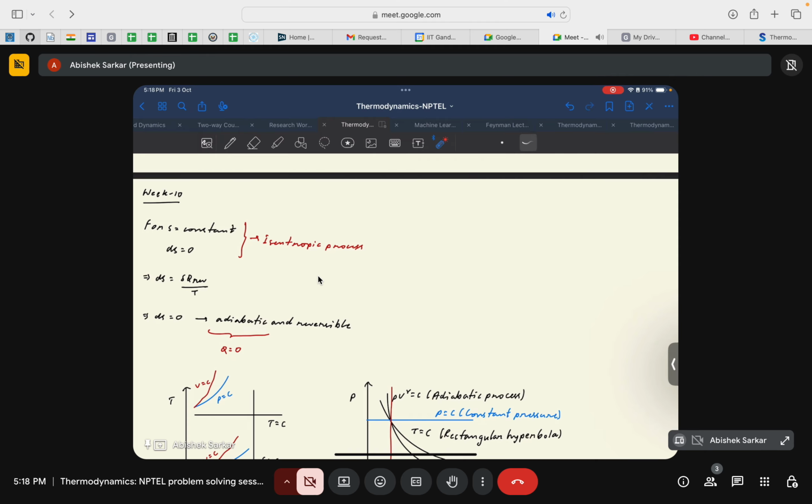Of course, it is, but a proper definition for entropy is clearly defined only for a reversible process, or in terms of a reversible process. So we found out that entropy, or a change in entropy in a more correct sense, is the ratio of the heat transferred in a reversible process over the temperature at which the heat was transferred. So that's the very definition of entropy.